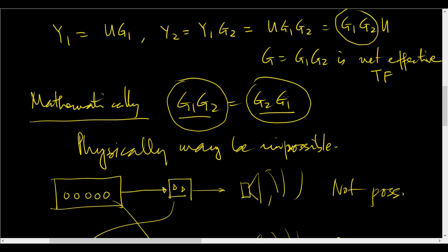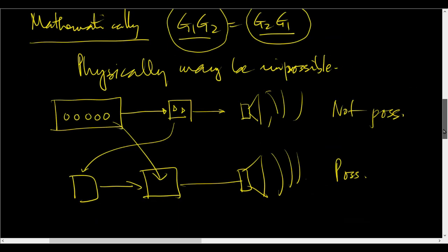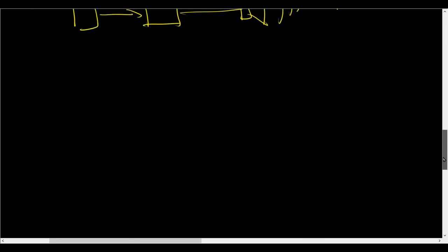Okay, so you have to remember that in the Laplace domain we can rearrange these blocks. In the physical world there are restrictions. There will be a part of your control system or your controlled system which will have small signals, little currents, little voltages. You have to remember that as an engineer. You cannot cross those lines or that sequence, but mathematically the sequence is clear.